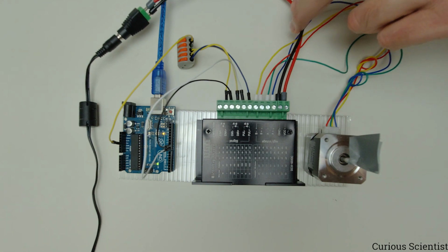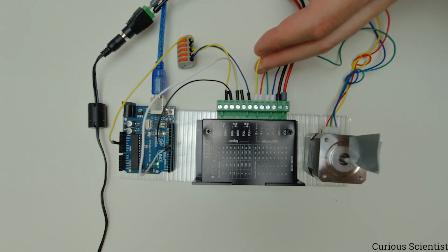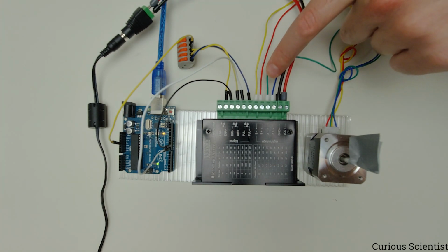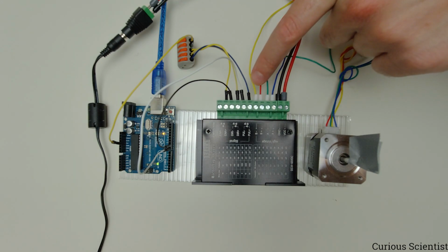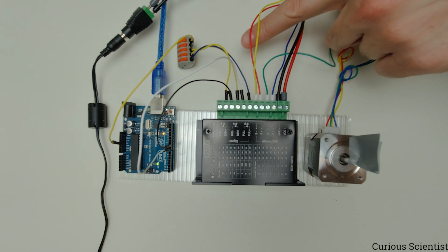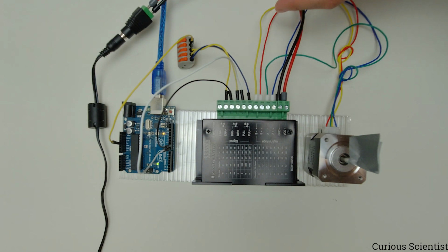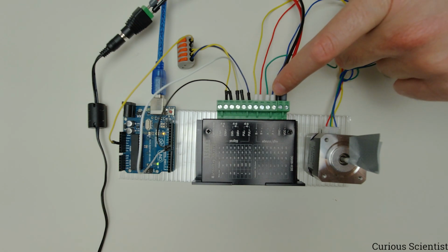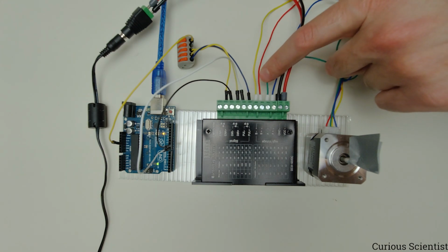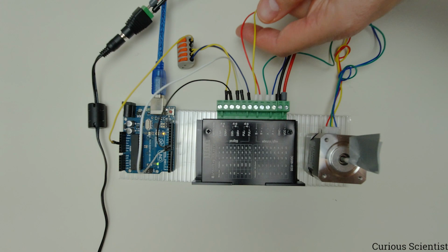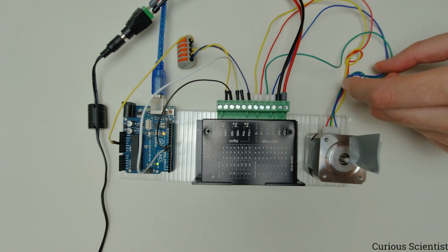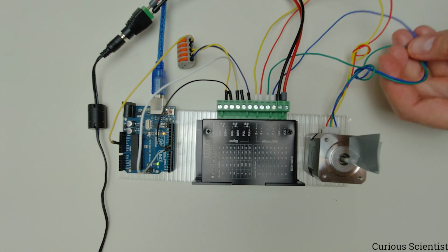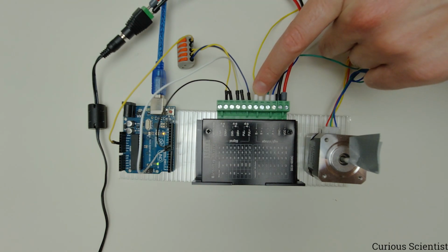Then we have the stepper motor. You can see yellow and red, they go together, so they make a couple. And then green and blue, they are also a couple. So this is one coil and another coil. The way you figure out which is which, you take a multimeter, you turn it into continuity mode, you grab a cable, and then you test the 3 other cables against it. When you hear the beeping, you know that those 2 cables, which are currently tested, belong to the same coil. So you put a loop or a knot on them, and you know that they are together. And you always have to put them together.